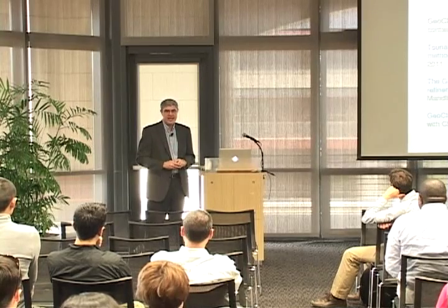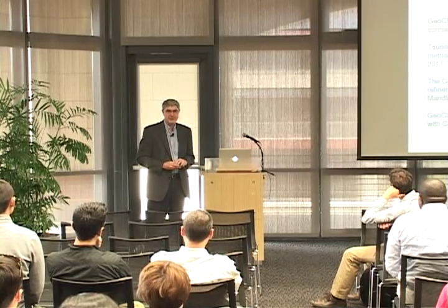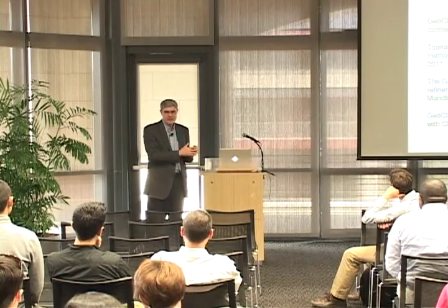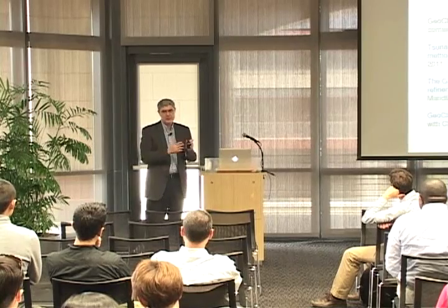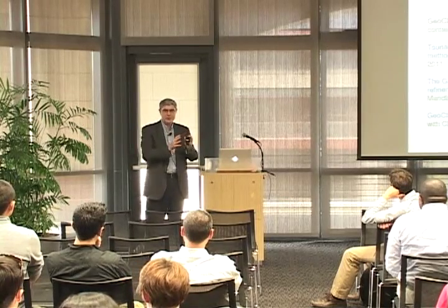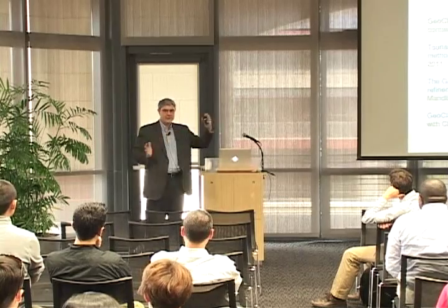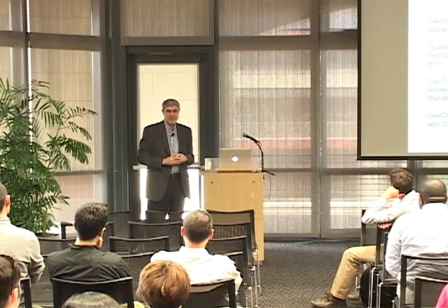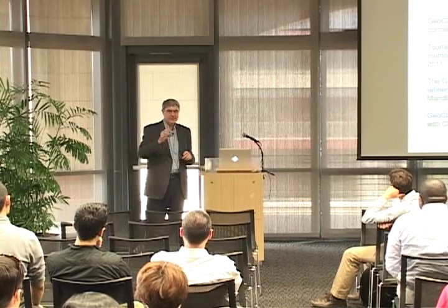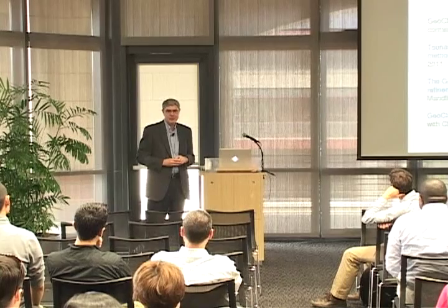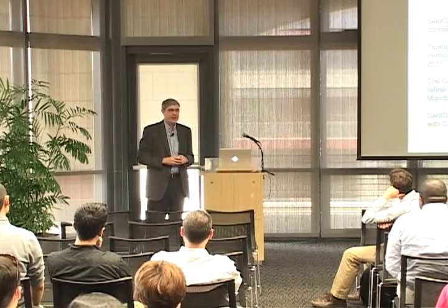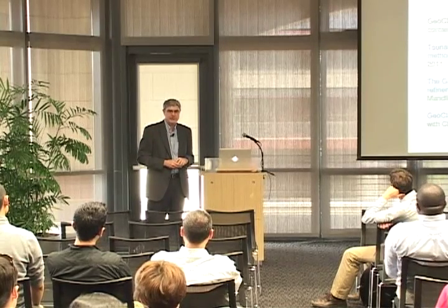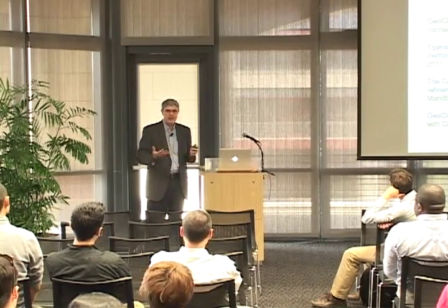We have been starting to look at adjoint methods for doing the adaptive mesh refinement. I have a student now who's starting to look at using adjoint error estimation, because if a tsunami is coming across the ocean from Japan towards Crescent City, of course there's the direct wave that you know you want to resolve, but there are waves going off in other directions that probably you can ignore, but maybe they reflect off of Hawaii and become important at some later time. So you'd like to trace back using the adjoint equation to figure out what regions you really need to refine in order to capture the waves that are coming in on the particular harbor of interest, for example. But for the tsunami modeling, there aren't really very many free parameters.